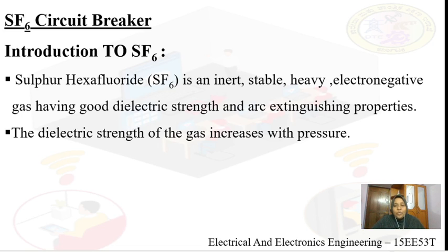That is why it is called an electronegative gas. And along with all these properties, it has good dielectric strength and arc extinguishing properties. So because of these reasons, SF6 gas is highly recommended for use in circuit breakers.